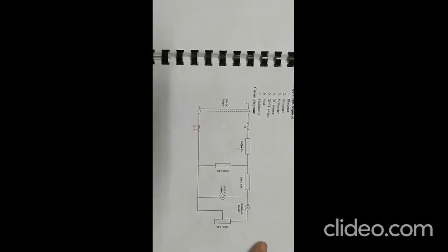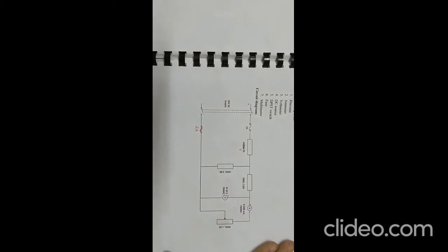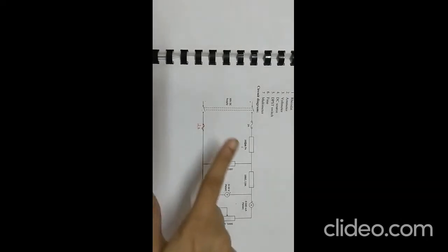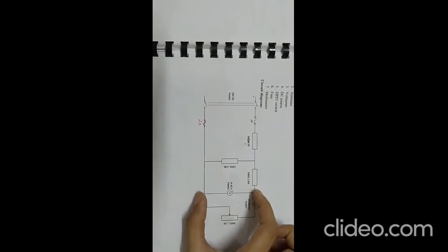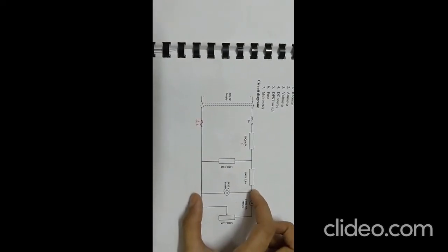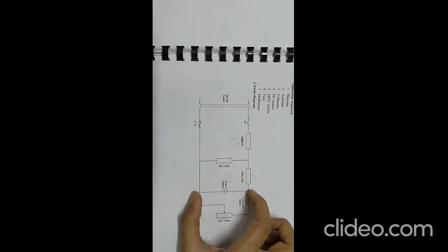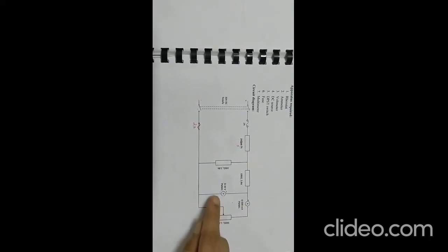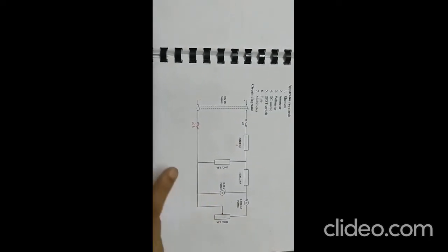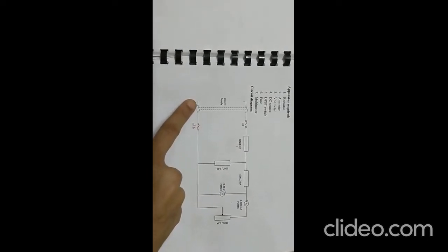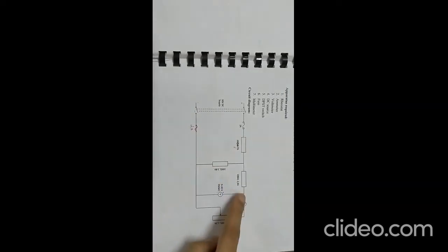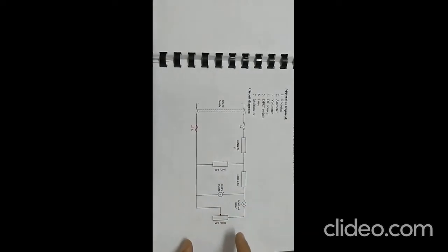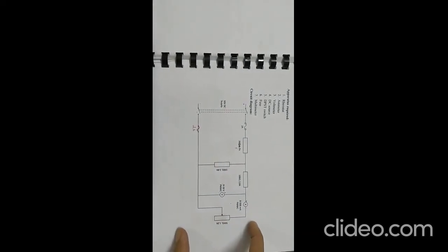We will be starting with the verification of the Thevenin voltage. We will wire up according to the circuit diagram you can see over here. We will be finding the open circuit voltage across the load terminals, so that will be the Thevenin voltage, and it will be indicated by this voltmeter. You can see that the supply over here is a DC supply, so we will be using moving coil instruments here, and all the resistances shown here are rheostats, which will be connected in fixed mode. So we can wire up the circuit.